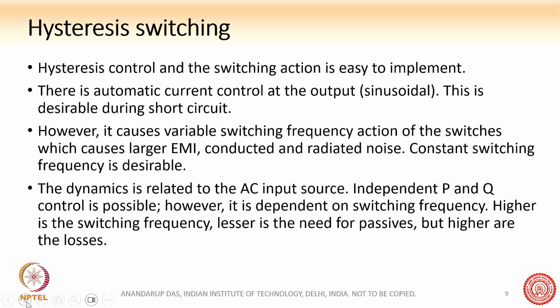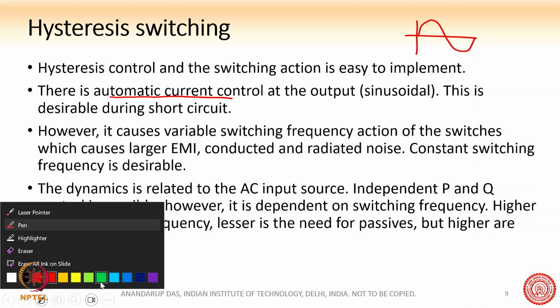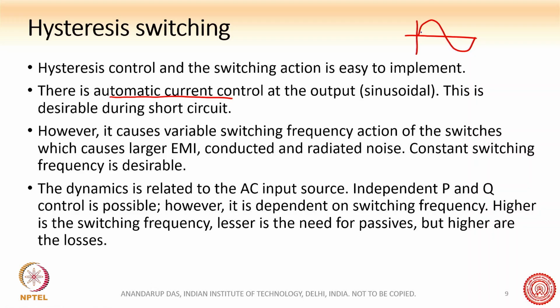So the hysteresis control technique is very easy to implement. Now this is important: it's an automatic current control. As long as your reference is a finite reference you have given, within a band, the actual current will always be tracked like this.